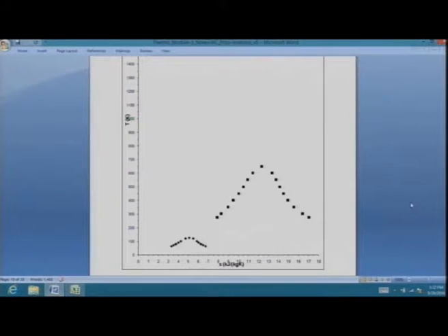I said that specific entropy of both substances at 0 Kelvin is 0. And with respect to that, I replotted SF and SG on the TS diagram. So now we are looking at a consistent set of specific entropy for two very different substances, whereas according to the tables, nitrogen is referenced to some temperature, water is referenced to 0.01 degrees Celsius. We cannot directly plot the two on the same diagram, but this is consistent now.